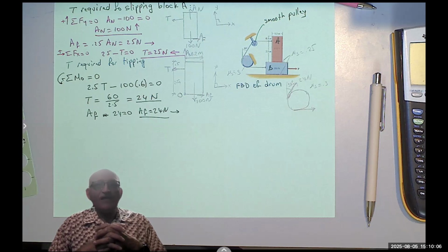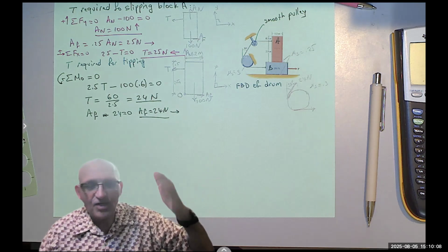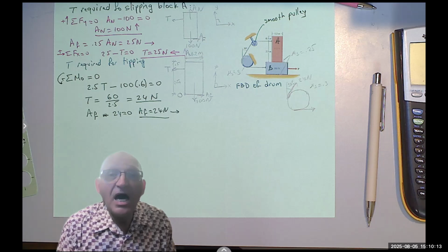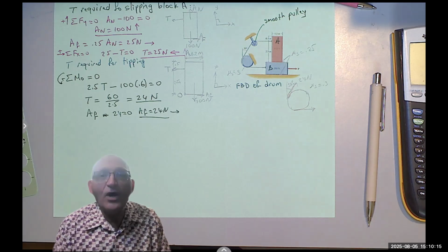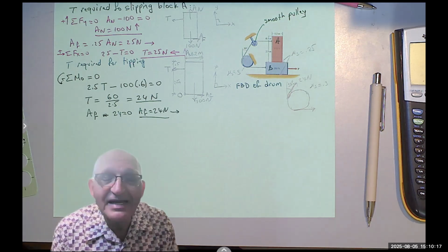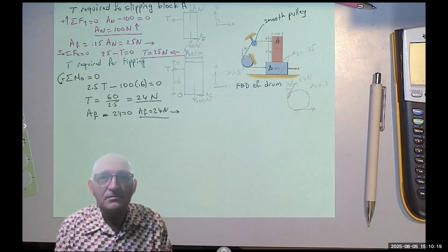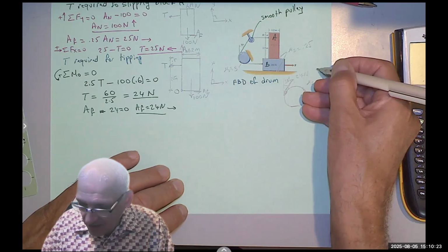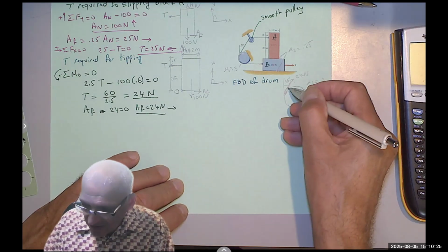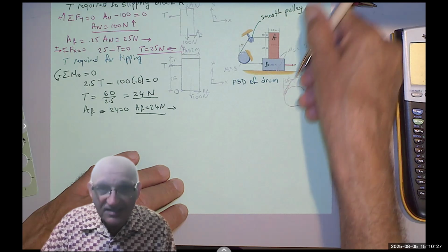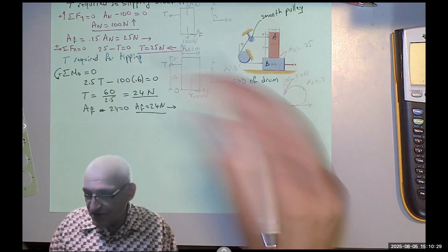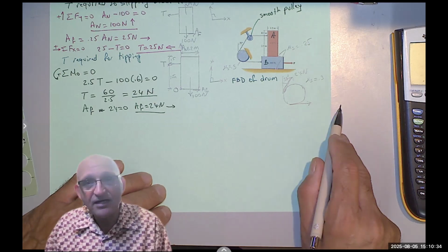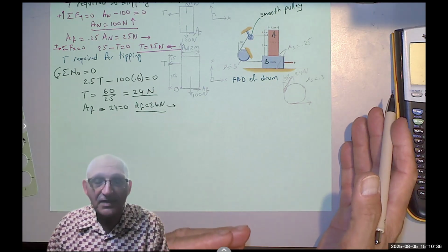Even if it's not a drum, think about it: the higher tension is always with the direction of motion. Meaning, if I pull, this thing would go down. You see the arrow is going up, but the motion is down. They are opposite to each other, so that is the lower. And the tension that follows the arrow, that's the higher.